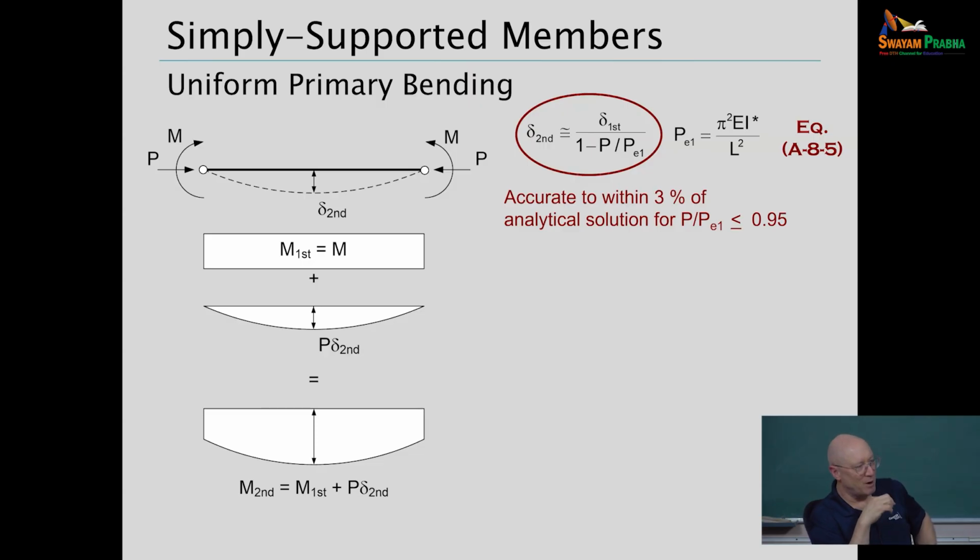But the subscript 1 is a notation that the AISC standard uses to refer to a braced buckling load or a non-sway buckling load. If you see the subscript 1, that's non-sway. There's also an amplifier that we're going to talk about, B1, that's for non-sway.